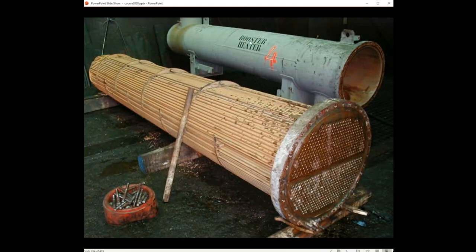So some people put here booster heater, and you understand why they put booster heater, although it has nothing to see with a booster. It's a simple cargo heater, but the booster because you use this heater always in combination with the booster, of course. So in this case, the cargo is flowing through the small tubes and the seawater is flowing around the tubes. Yeah? That is the exchange of heat. Therefore, you need a maximum contact surface, and that is achieved by the use of these small tubes.